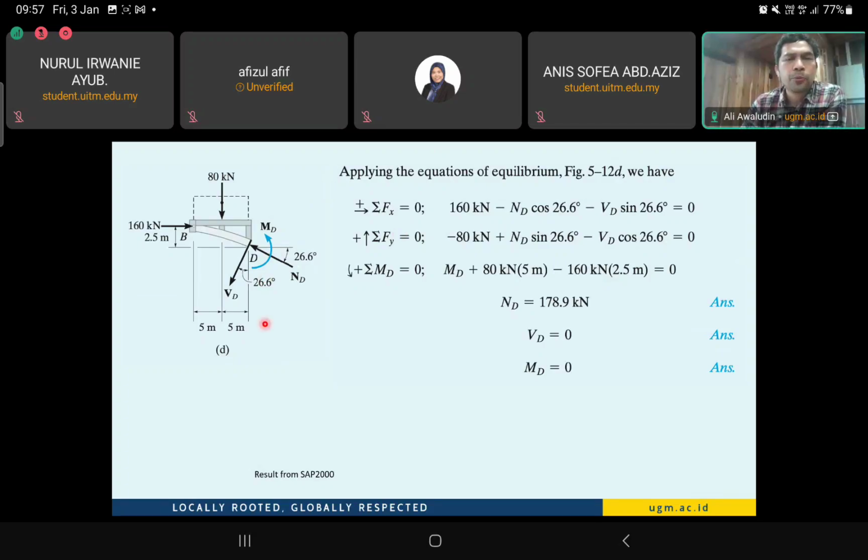Okay. Then we use the same things. Vertically it has to be balanced, because for equilibrium the vertical forces, the horizontal forces, and also the moment must balance. The summation of the moment at point D is not what we are looking for, but the summation of moments must be equal to 0 at any point. Actually, it should be equal to 0, but D is not the pin or the hinge. Then the summation must be equal to 0.